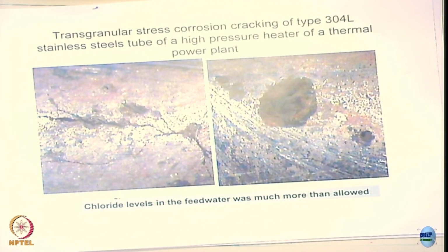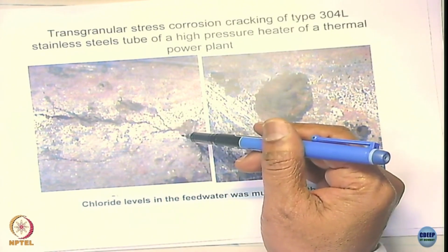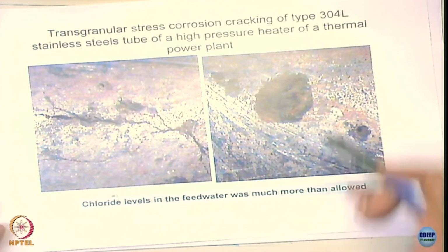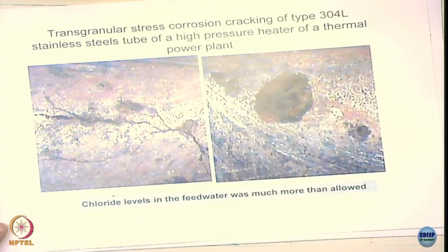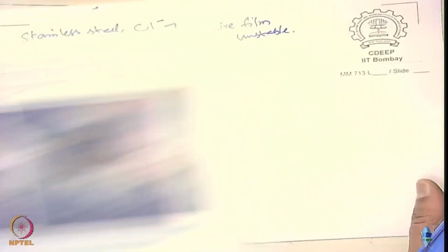The pitting occurs. So the chlorides do help to damage the film, and when you form a pit, they become stress risers and lead to stress corrosion cracking. We discussed earlier that stress corrosion cracking involves initiation, right? And the initiation process involves, we say pitting is one of the precursor events. You see the pits, they are responsible for stress corrosion cracking. It can happen, and so they are the problems.